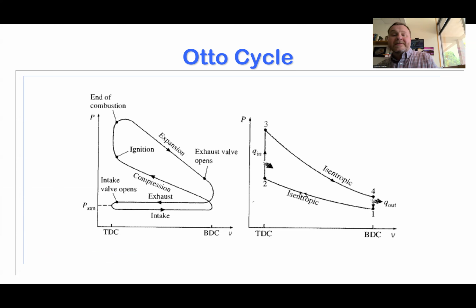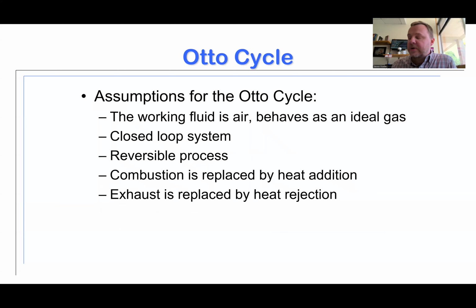So it's all that to say that if you take away this bottom loop, notice that these two diagrams very, very closely mimic and match each other. Just understanding that as we approach reversible, the area of this secondary loop approaches zero. Okay. All right. So again, the Otto cycle we're going to use to be a very good approximation comparison of what a perfectly ideal reversible internal combustion engine using a spark plug would look like. The Otto cycle is what we will use to do so.